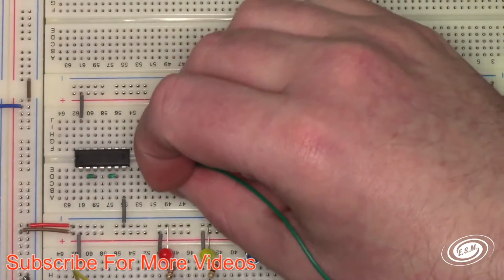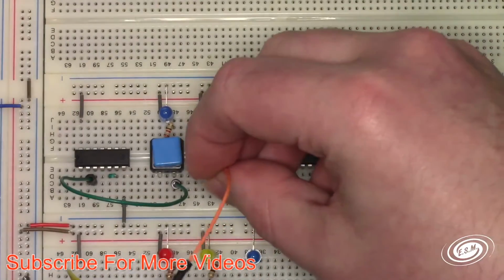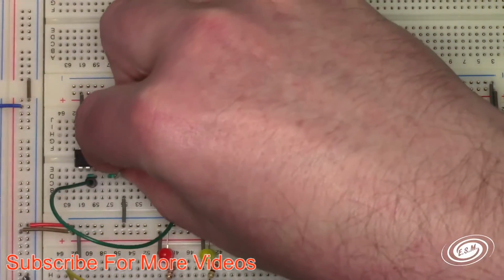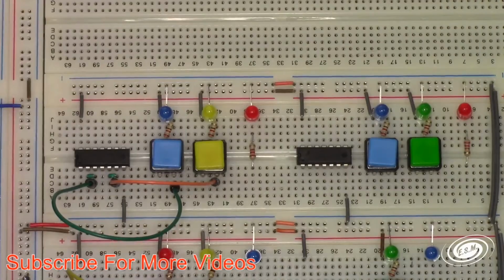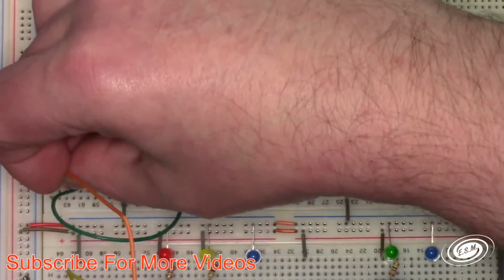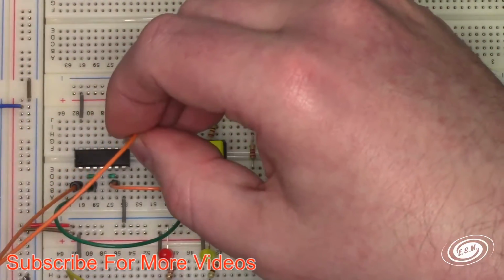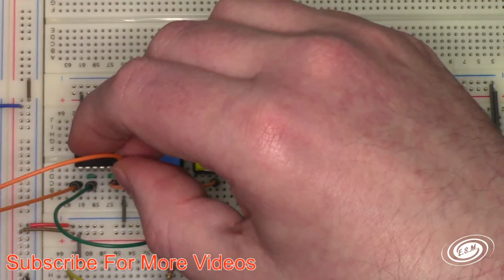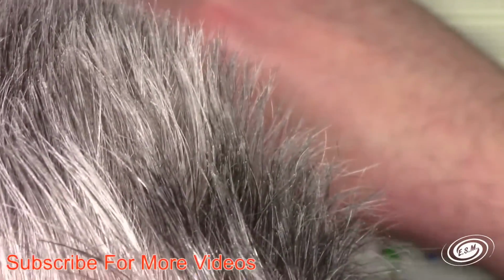I'm going to go to my A output, and I'm going to plug it into this first one at pin 3, this one into pin 6, and now I'm going to take my output from that NOR gate, which is pin 1, and I'm going to tie it to pin 11, which is the input for my second NOR gate.